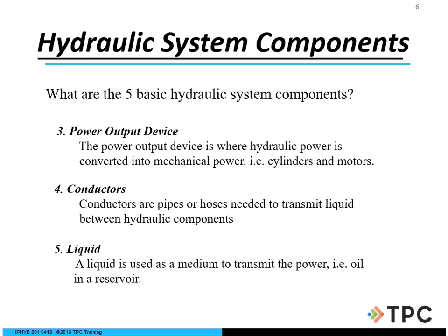Okay, well, how much liquid, how much oil do we actually need? And so usually we need to find out, what is the flow rate? What is my gallons per minute of oil in my system? What you want to do, this is a small formula here that you can really write down or look at. So what we want is 3 times the flow rate is going to tell us the size of the reservoir. And so that way we're definitely going to know that we need this much oil so we don't run out of oil, right? Run out of hydraulic fluid in our system.